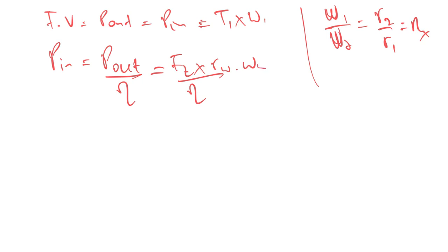The wheel angular speed. Okay. So this is the definition of the output power, right? If you multiply the tractive force at the wheel times the radius, as I indicated before, times the speed of the wheel, you get power. This whole gives you power, but still the output power. Okay.